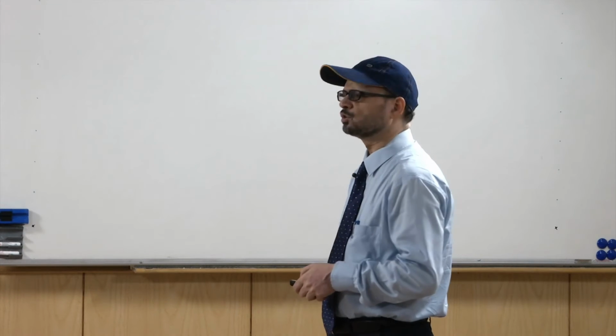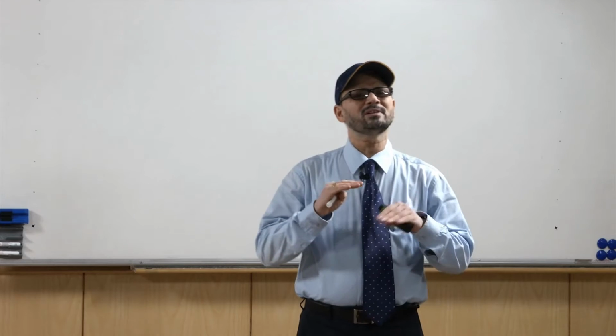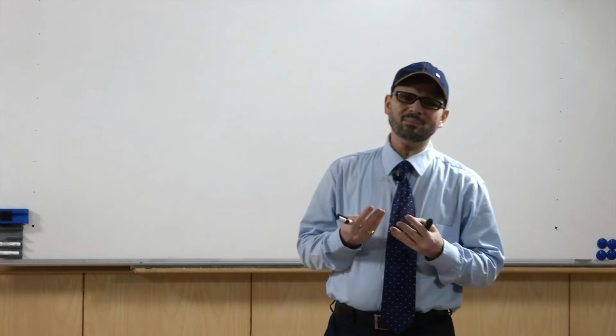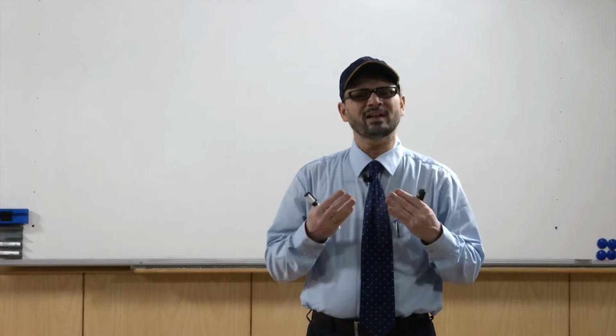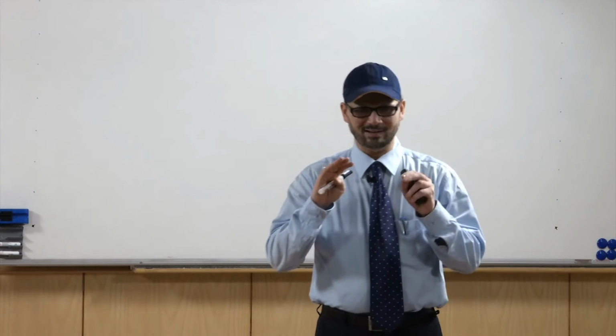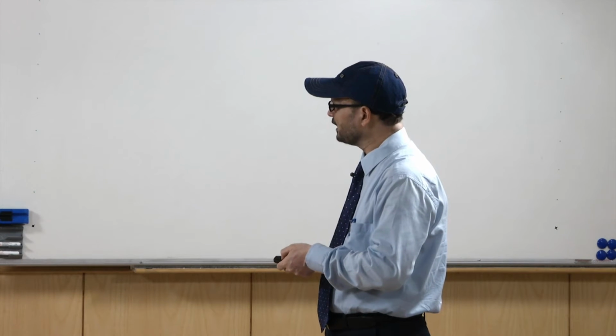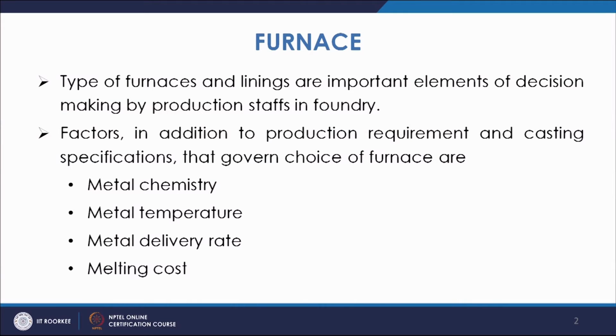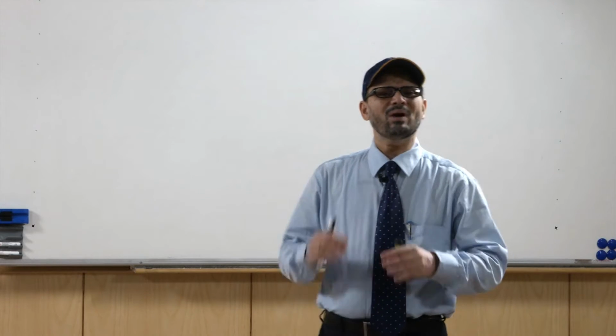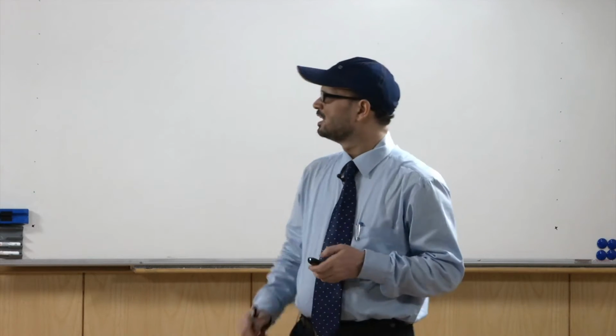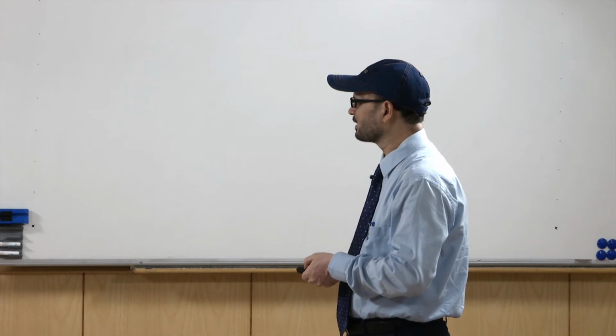Metal delivery rate: at what rate do you want the metal to be delivered from the furnace? What is the requirement of the metal in terms of tonnage and the amount of metal in a particular time? That is the metal delivery rate. You need the furnace to deliver the metal at the rate you want, at a particular temperature, and at a consistent rate. So you have to decide what delivery rate of metal you want, and based on that you decide the type of furnace.